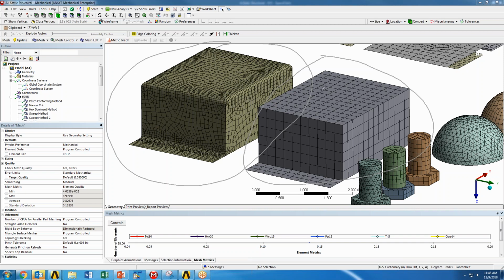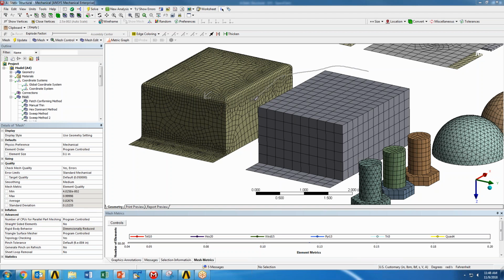Depending on the mesh control, if you have a mesh control that respects curvature, that is going to very finely mesh the curves because it's trying to capture them accurately, versus if you just remove them, you get a much coarser mesh for the same part that's going to be more efficient. I can say from experience that having these fillets in here is not going to impact the resulting stress concentrations really at all. If you truly care about it, you can always do a test case where you have 2 parts like this, apply the same loads, and deeply analyze how having the fillet there and not having it there impacts the resulting stress on the body.